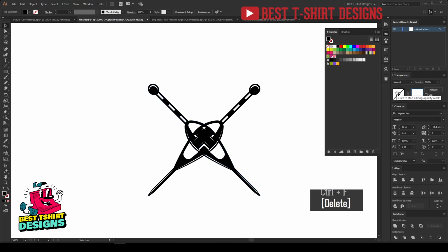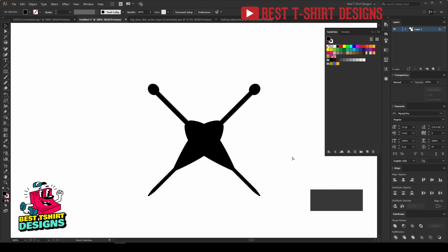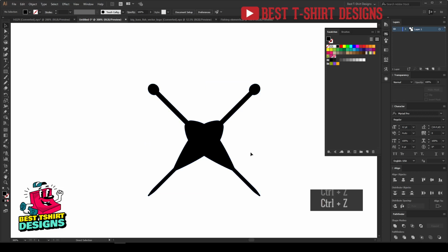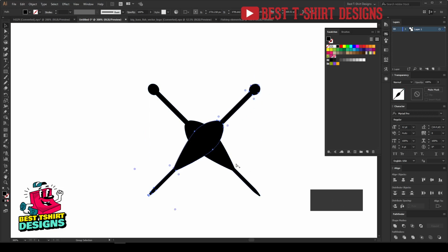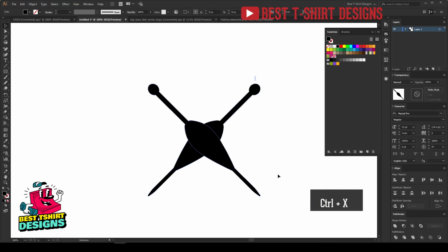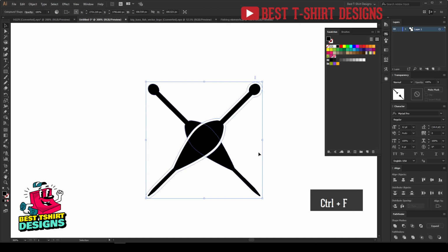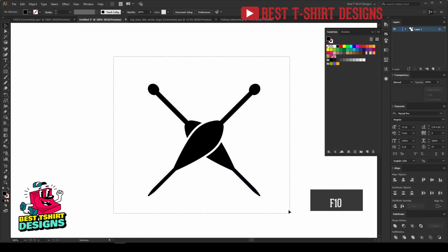Okay guys, I don't need to do that. I'm just going to select this and merge, unite, so it will become one single shape. Okay, before that, sorry, just merge it, unite. I need to do it one by one. So here is the first one, merge unite, and then this one, merge unite, and then I am going to create an offset path for that, but a bit smaller size, cut it, select this one, and then press Ctrl F, again press shift to select that one, press minus front. So this is how it is looking right now.